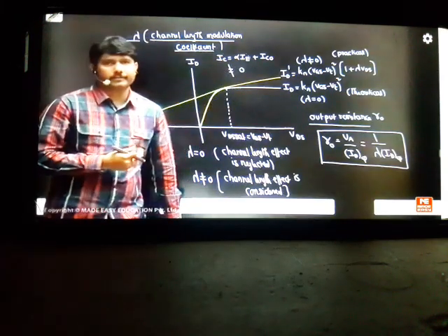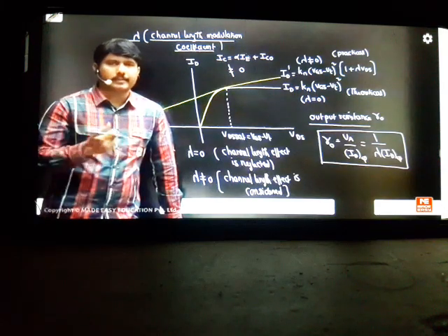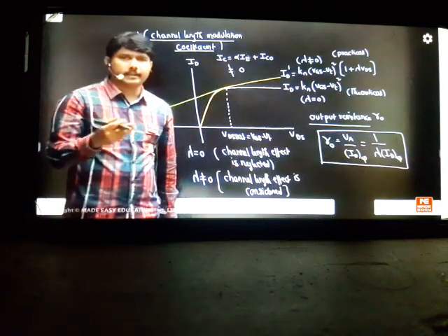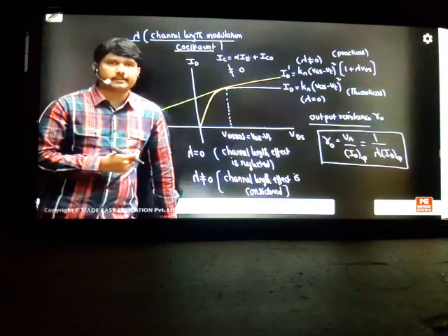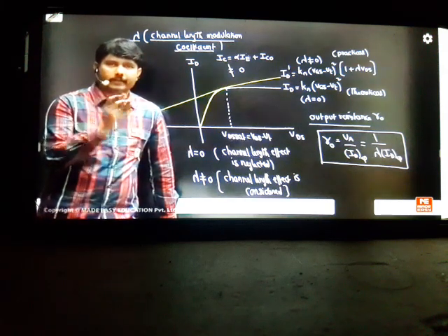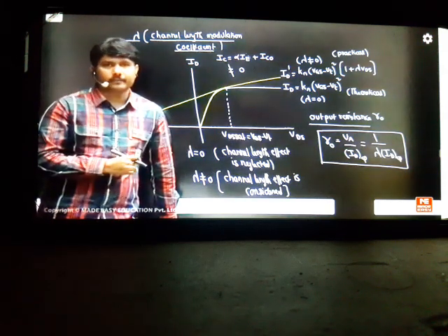Rahman, I hope you recollected the knowledge. Whenever a reverse bias voltage is applied, you are saying that the IC current will become 0. Use the theoretical knowledge here. We have majority current plus minority current, which we studied in our previous basic classes. In the fundamentals, we studied that alpha IE is the current coming from the input emitter, and IC naught comes from the reverse bias voltage.